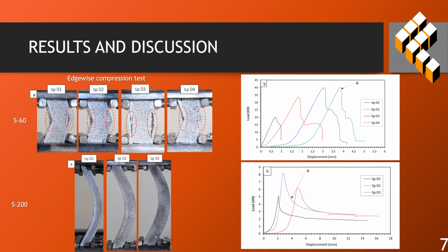The tests revealed a variation in failure modes depending on the geometry of the samples. When the length of the specimen is equal to its width, localized failure modes are observed, including skin buckling, skin core debonding, shear sliding of the skin, and localized buckling followed by skin cracking.